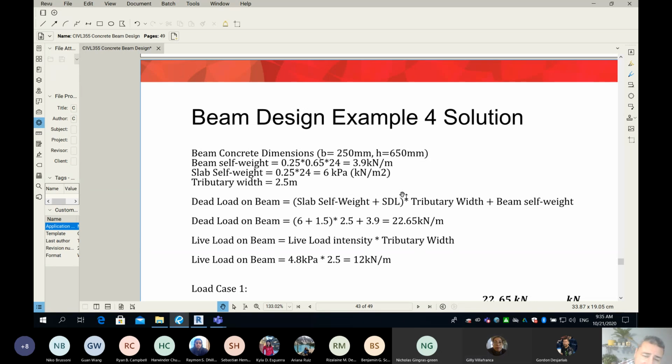Again, please, in the exam or midterm or assignment or anything, before you say something, just read the plan view. If those are given to you, please don't assume anything else. I get really mad when I see students just go ahead and use the table. Remember the table that I taught you on how to find the thickness or the depth of the beam? Don't use this one. Use it only and only if the depth of the beam is not given.